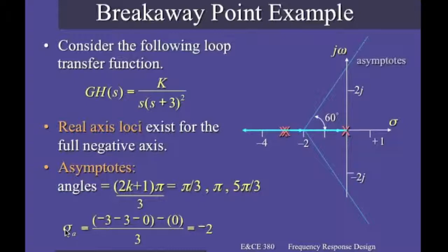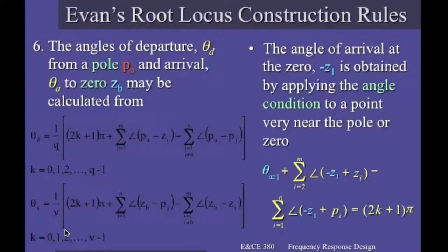at the denominator. So the fact that we have a double root or a double pole at -3 is noticed here by double crossing that point. So there are 2 overlapped, almost overlapped crosses. So we may land on the final Evans rule, which is rule number 6.